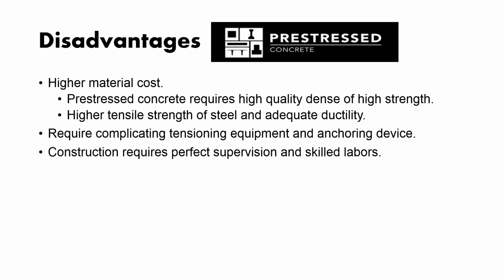So what are the disadvantages? Of course, it has a higher material cost. Pre-stressed concrete requires high quality, dense concrete of high strength, and higher tensile strength steels with adequate ductility. It requires complicated tensioning equipment and anchoring devices. So you need to have the devices, else you cannot do it. Construction requires perfect supervision and skilled labour. So you need a good supervisor, good engineers, and skilled labour to do the work.